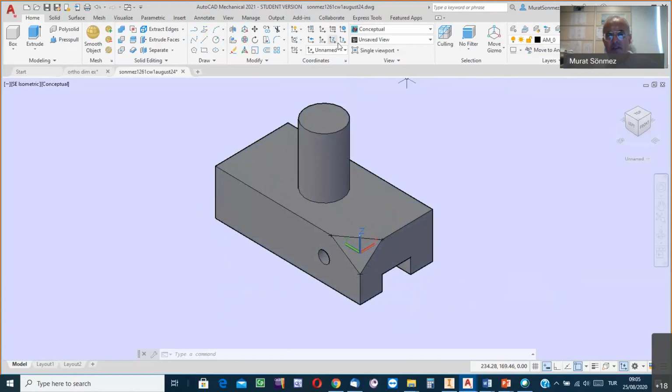How? You know my favorite method, the 3-point method. Click on this button. Yes, you see I took a right to move the coordinate frame. The system in the first compartment is asking me where the origin is. Origin of the coordinate system. Of course, the snap enabling button is on, and you have already enabled the software to indicate the terminal points, endpoints.